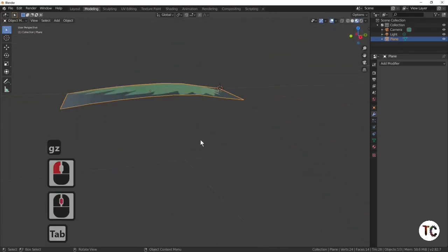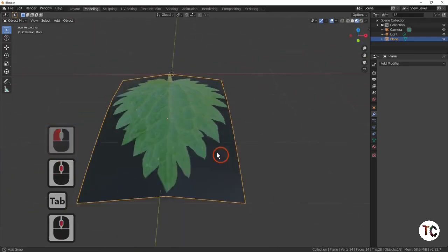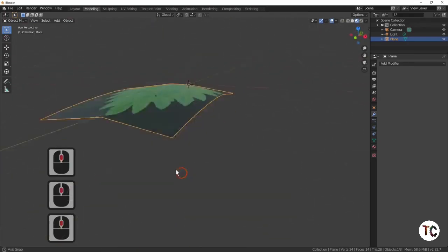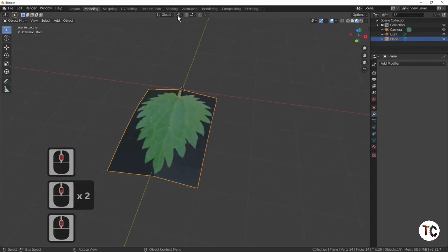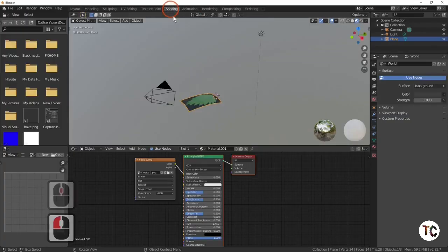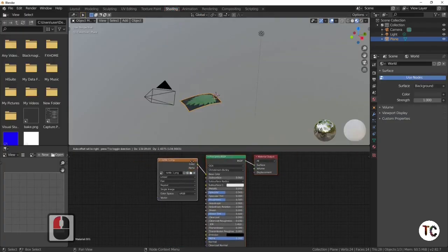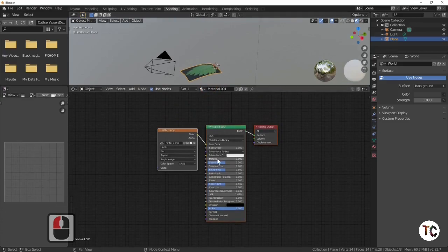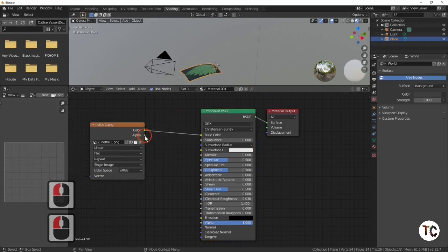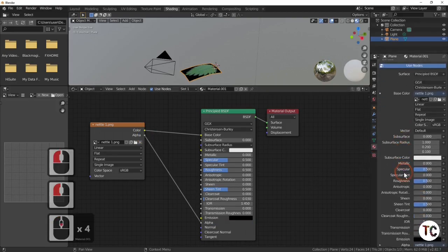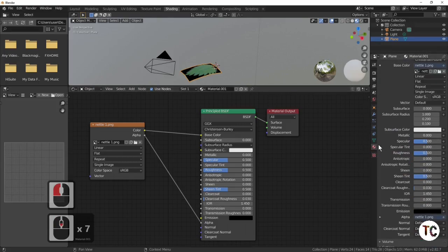And now what we've got there is the shape of the leaf, but as you can see, these bits are not see-through, but we have made a transparent texture. So if we just go into the shading tab, and we'll shrink that image up a bit so we can see it. What you've got there is alpha. Because we saved the actual image in the PNG format, it has got an alpha map on it, so select that into the alpha map and then go into the actual substance or the material,